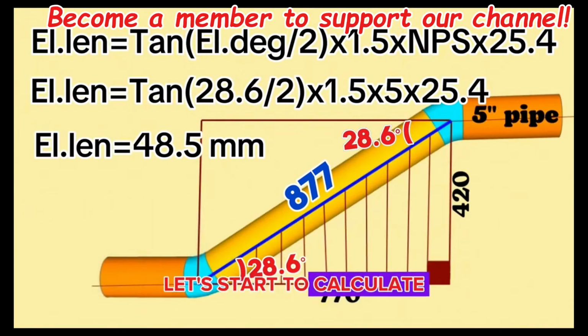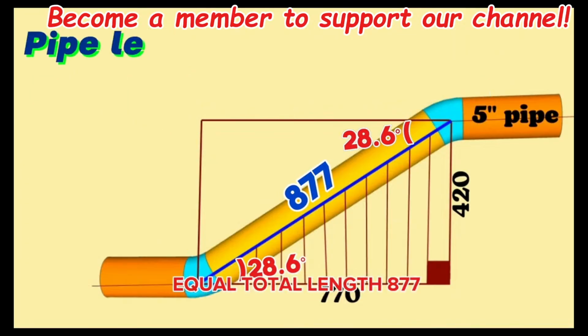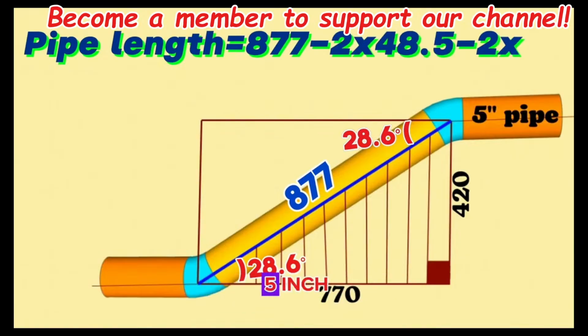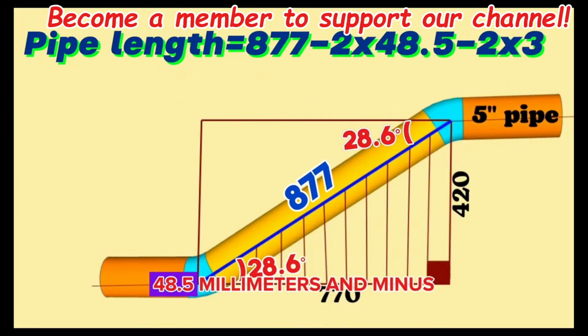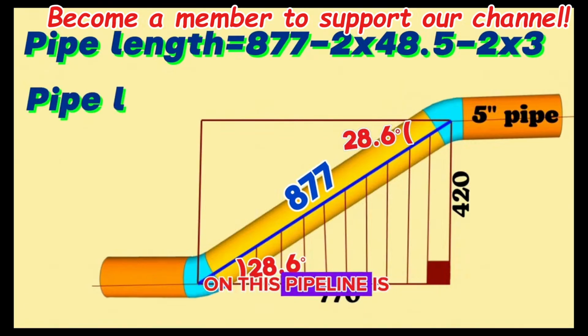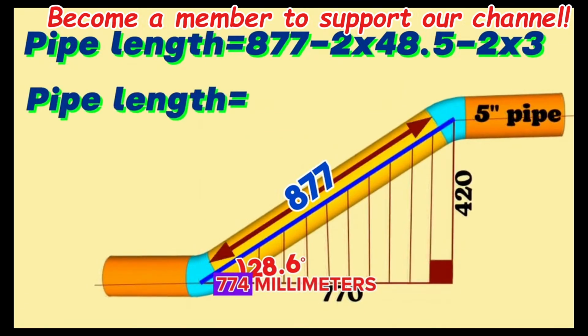Let's start to calculate this yellow color pipe section length. Pipe length is equal to total length 877 millimeters, minus 2 times 5-inch 28.6 degree butt weld elbow length 48.5 millimeters, and minus 2 times gaps for welding 3 millimeters. At last we calculate and found the length of the 5-inch yellow color pipe section on this pipeline is 774 millimeters.